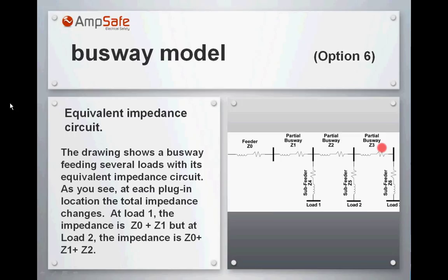That will create a lot of work. If you have the exact impedance, then no problem, because you will calculate the exact arc flash incident energy here, and at that bus plug, you could put an arc flash incident energy label, and this one will be different because the impedance is different, you would provide another label with a different result than this, and so forth, okay?